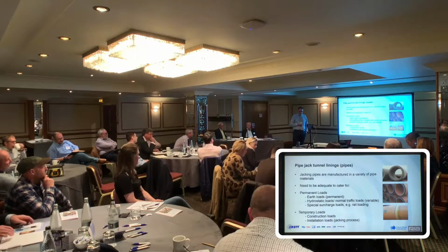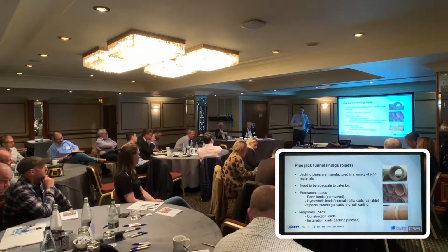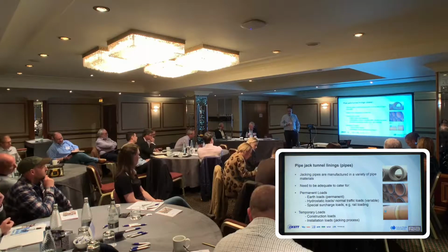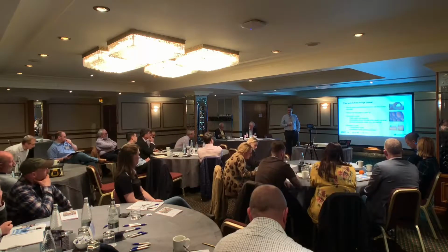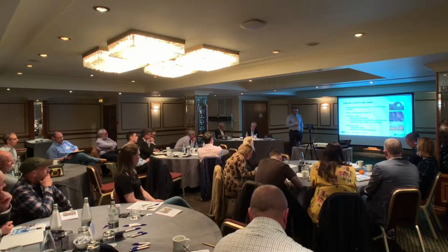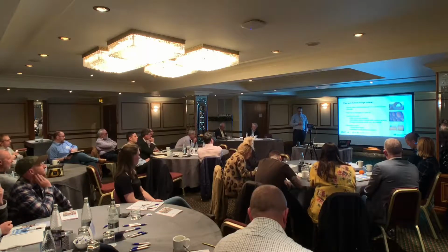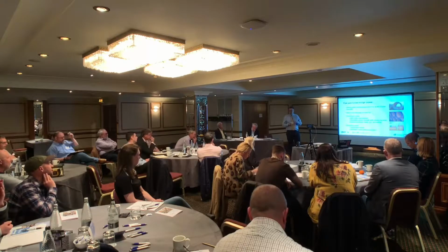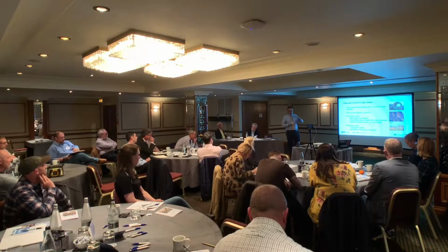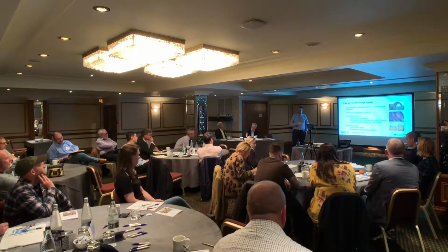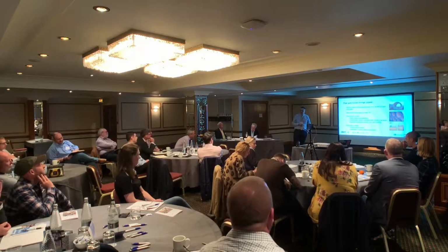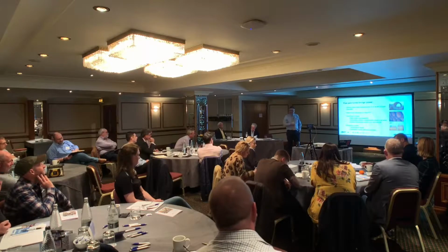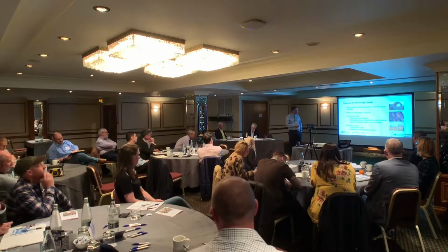There are other documents, such as in the back of a document called BS EN 1295, the guidance for the design of buried structural pipes. They've got a series of nomographs in the back there, for want of a better term, so that for the depth of cover and the type of railway you've got, whether it be mainline railway or what they call light railway, you can read up and define the surcharge loading.